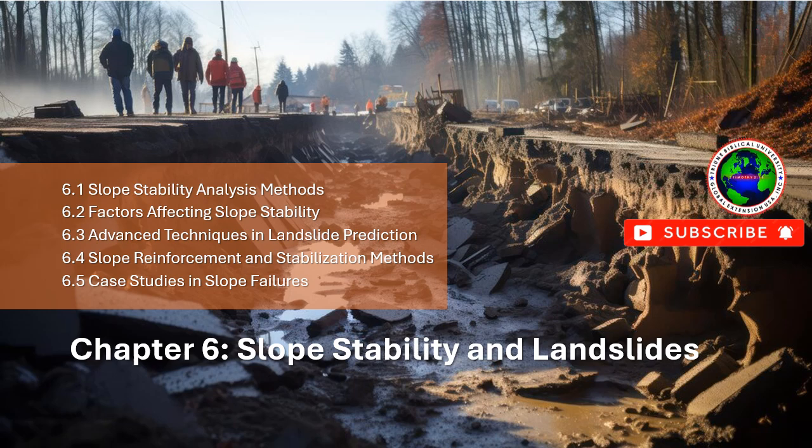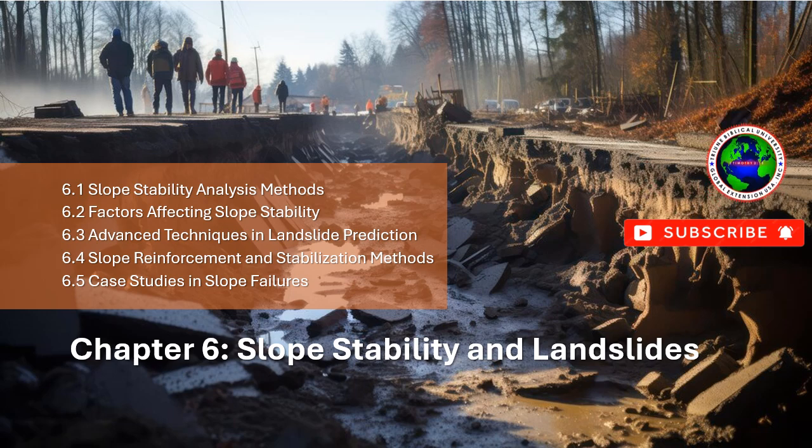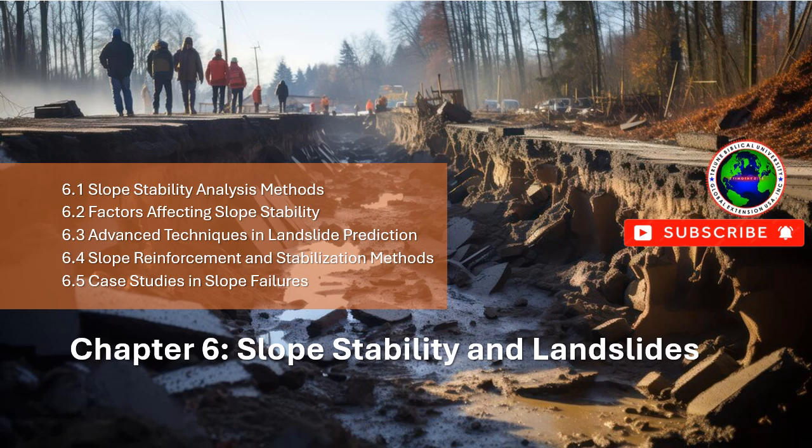Mitigation measures. Slope remediation. After the disaster, authorities removed the remaining slurry heaps from the area and undertook slope stabilization measures to prevent future incidents. Stricter regulations. The Aberfan disaster led to changes in mining waste management practices in the UK, with stricter regulations governing the construction and monitoring of slurry heaps.